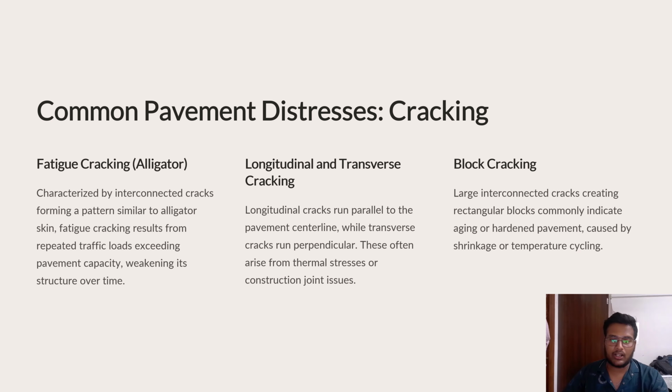The common pavement distresses. The first is fatigue cracking, often called alligator cracking. Resembling reptile skin, it is caused by repeated traffic loads that exceed the pavement capacity and is common in older or overloaded roads. Then the longitudinal and transverse cracks.